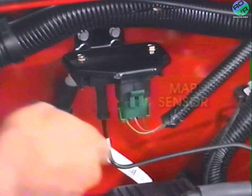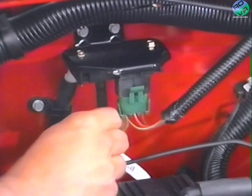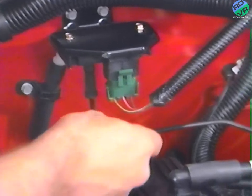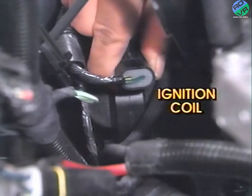If the engine controller connector passes a visual inspection, you can then move on to inspecting the rest of the system's components. Be sure to check all the electrical connections and vacuum lines used on the sensor inputs for the engine controller. Here's a sample of what to check for when performing a visual inspection. On inputs such as the MAP sensor, check the electrical connector. Also verify that the vacuum hose is connected to the sensor and to the intake manifold. Check the ignition coil connections and verify that the coil wire is connected to the distributor.